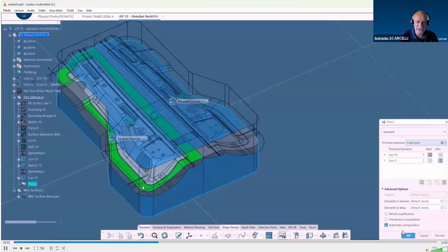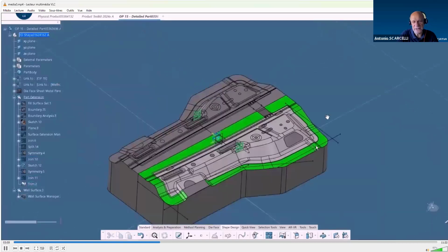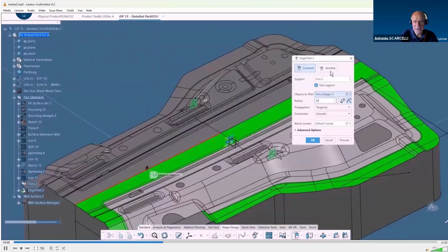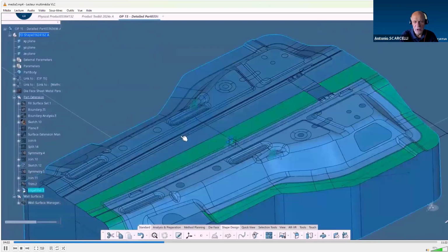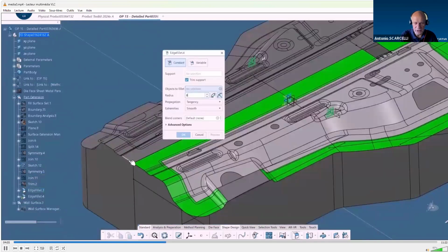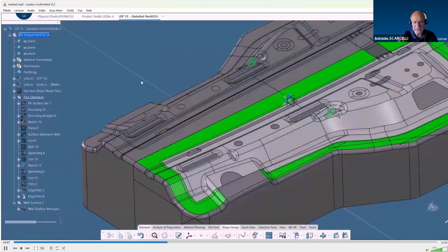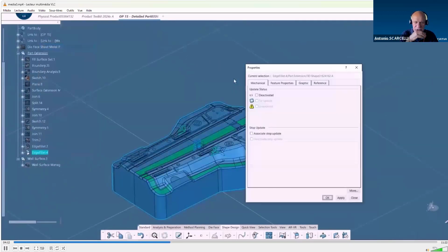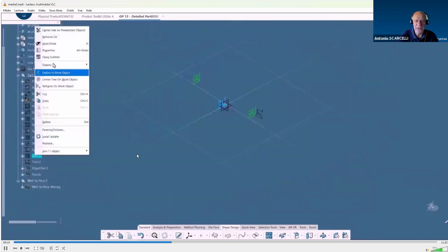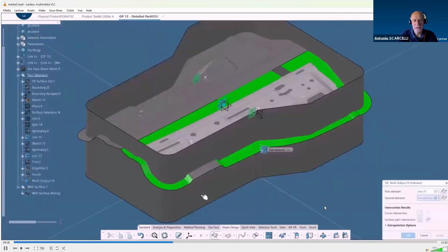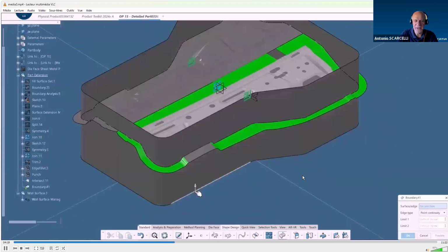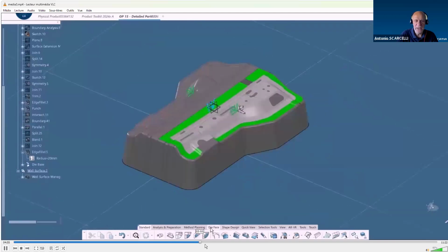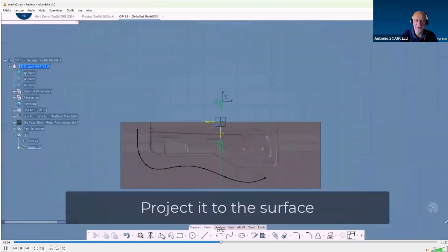At each intersection, the system is generating a fillet, and you can manipulate this value. You can manipulate the value of the wall and the fillets globally, and you can manipulate them locally. So one by one, you will be able to modify it. You will generate the fillets and so on. You will prepare your die face, as you can see here. Okay, and at the end, you will get your die face.